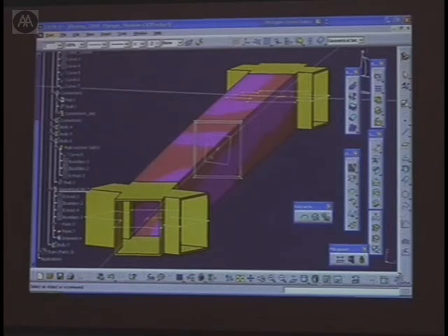The problem is that, again, never mind the software, you have to think as an architect here, or in this case almost as a structural engineer. These joints, the plates on the top and on the bottom, are flat. They're flat pieces of steel plate. They vary anywhere between 40 and 130 millimeters thick, depending on the torsion that they're getting, but the joints are actually flat.